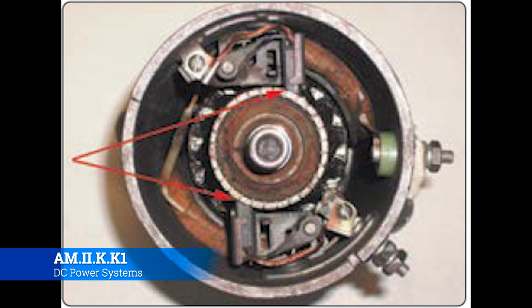You want to make sure that every single one of those doesn't show any sign of corrosion, any sign of breaks or cracks, or anything that's going to cause the generator to fail, or even more so if the wire is starting to break internally and it's basically shortening. That means that it's going to get hot, and that could potentially lead to a fire. So you always want to check that kind of thing. Make sure that it's clean.